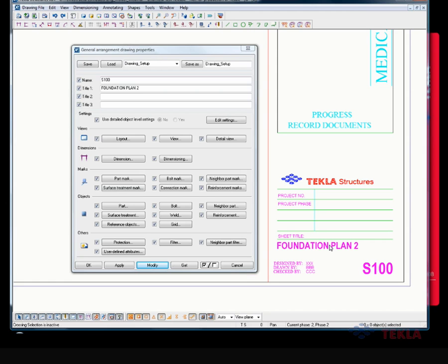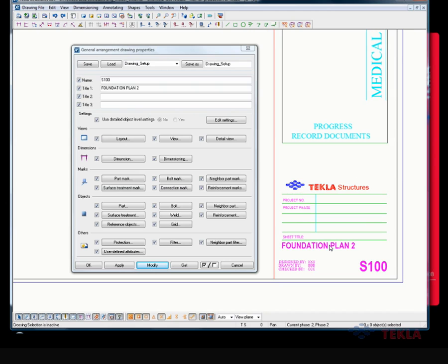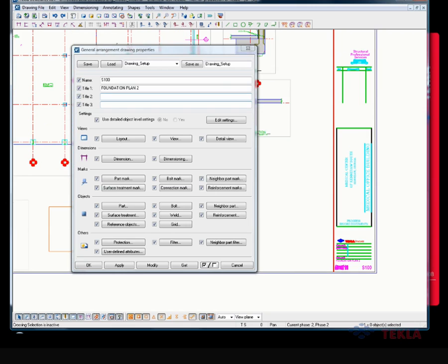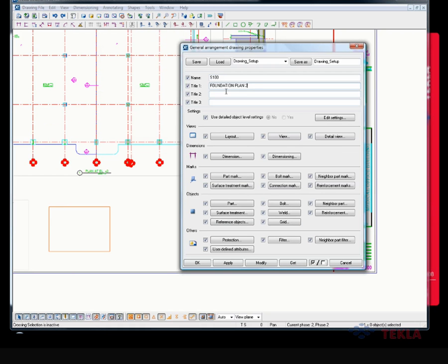was about how to set up your title blocks, and in that video it was showing how to map your sheet name and sheet title information into the template editor. So we have examples already of title block templates that you can use to see how that works. But the information, again, from the drawing sheets goes directly into that location there. So pretty straightforward, and if you needed more specific information, like more title information, you could include that as well.